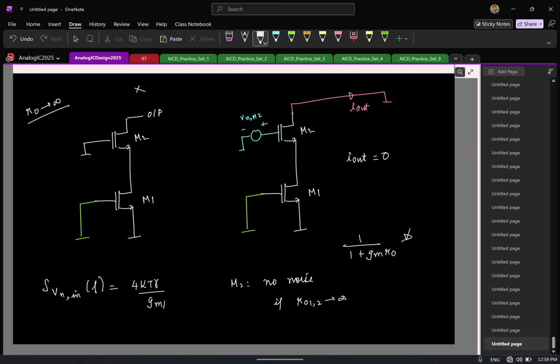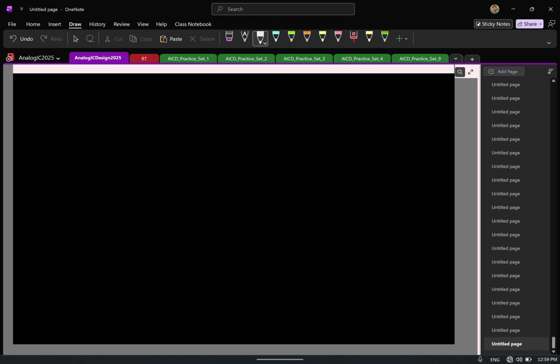Okay, cool. So now basic noise calculations, hopefully you are comfortable. So let's look at our op-amp topologies and see what the noise in our op-amps will be. So let's start with the first candidate. What was the first op-amp topology we saw? The 5 transistor OTA. So let's do that. So let me draw this. PMOS, NMOS, then we have this.